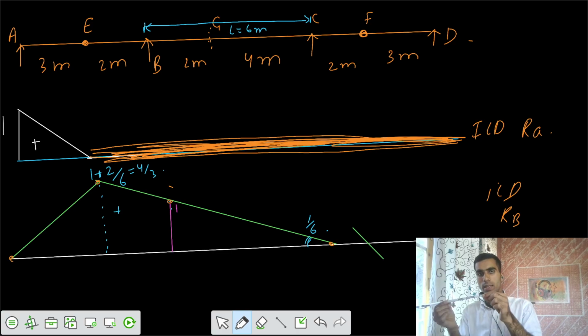So this is your point C now, and after that there is point F, and support D is here. That means once your C is on the original line, support D has to also remain at the original line. That means the hinge has to show some rotation theta 1, theta 2, such that point C and point D are at the same level, the original level. So this should be the profile after the point C.